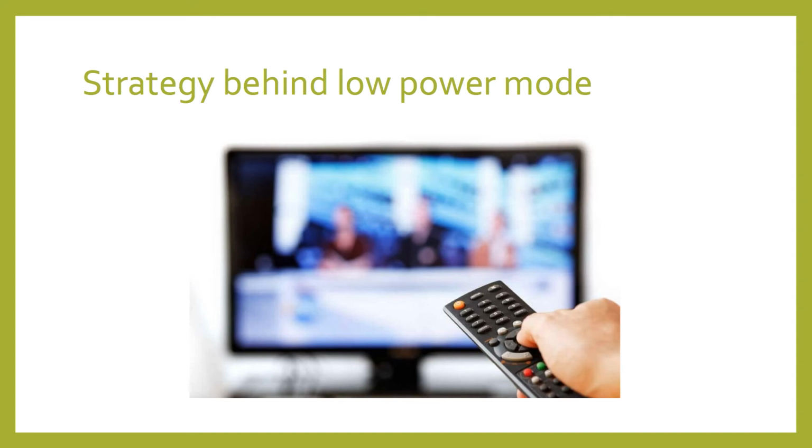On a television, for example, when you push the power button on the remote control, you're not really turning the power to the device on or off. You're actually signaling to the television to go into or come out of low power mode. When it's off, the television still retains some power since it needs to monitor the remote control to see if there's an interrupt event to wake it up. So when you push the power button on the remote control, the receiver gets the event, issues the interrupt to the sleeping system to wake it up and power everything back up.